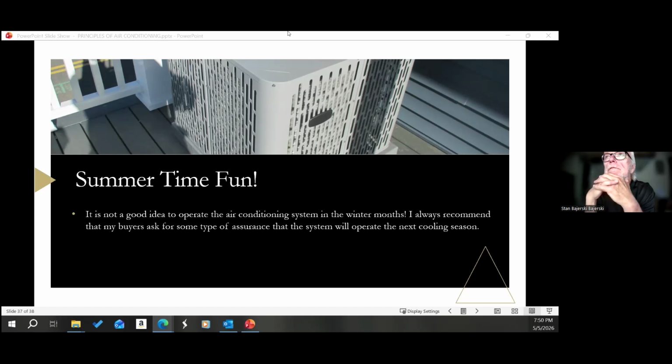Now she didn't realize that with our system, from wherever we want the temperature down to about 40, 42 degrees, the heat pump's going to kick on, and we're heating the house by forced hot air. Below 40, 35 degrees, whatever the temperature is, the boiler kicks on and the baseboards heat up.